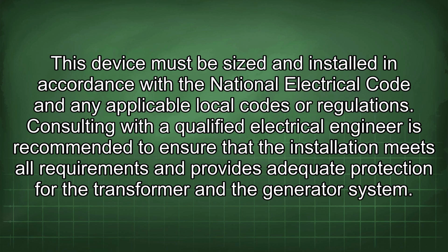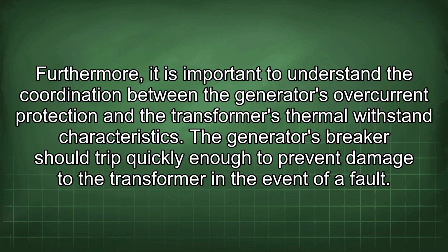Consulting with a qualified electrical engineer is recommended to ensure that the installation meets all requirements and provides adequate protection for the transformer and the generator system. Furthermore, it is important to understand the coordination between the generator's overcurrent protection and the transformer's thermal withstand characteristics. The generator's breaker should trip quickly enough to prevent damage to the transformer in the event of a fault.